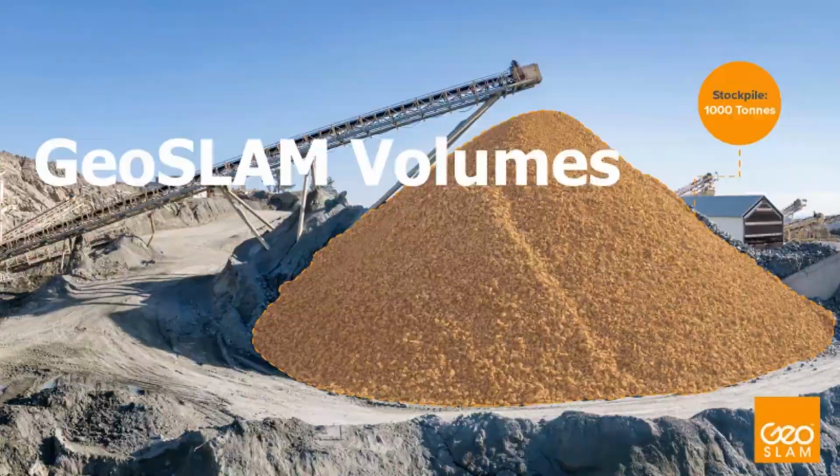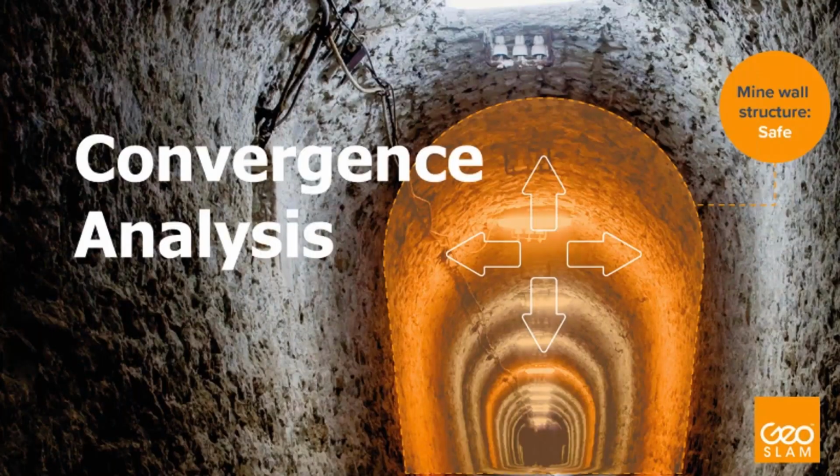We have a workflow for convergence analysis as well. Like I showed, Connect does have a change detection tool in it, but some people like to use third-party software. As long as we can provide you a clean georeferenced point cloud in the right format, you can do all these applications with it. The critical part is obviously the georeferencing and the cleaning of the data.